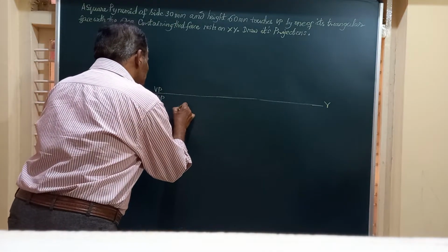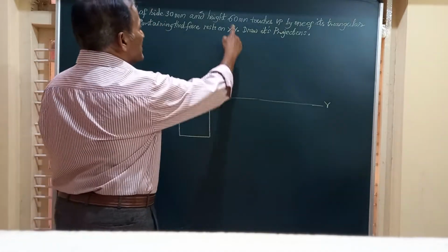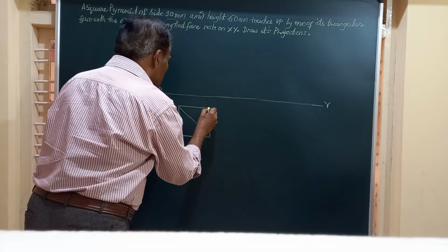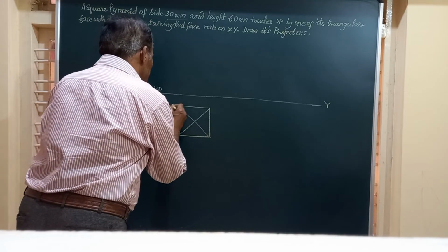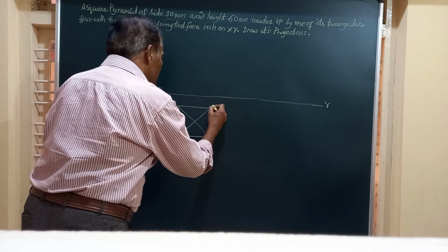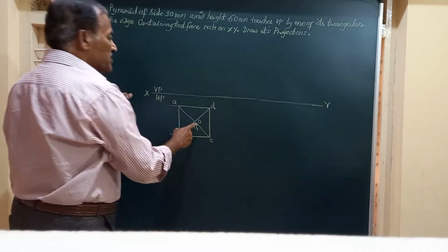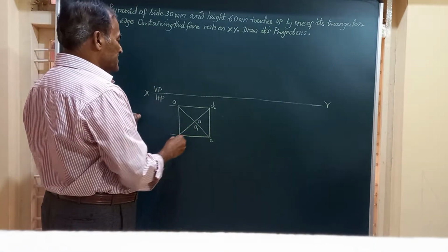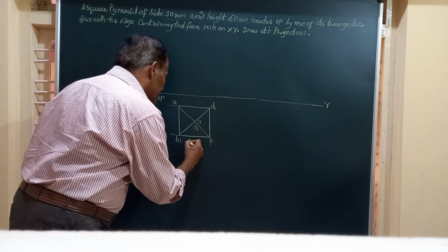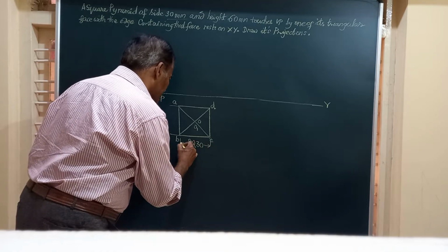So I am going to write down a square here of side equal to, you can see 30 mm side. So I am going to join these diagonals and mark this as ABCD. ABCD is the base of the pyramid, and I'll mark here O comma O1. O is for the vertex and O1 is the center of the base. And each of these sides measure 30. I will say SQ30. SQ indicates that it is a square of 30 millimeter side.